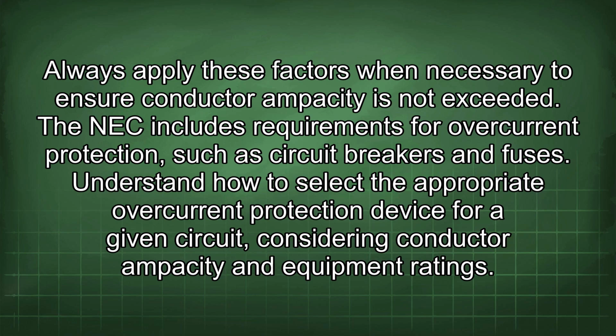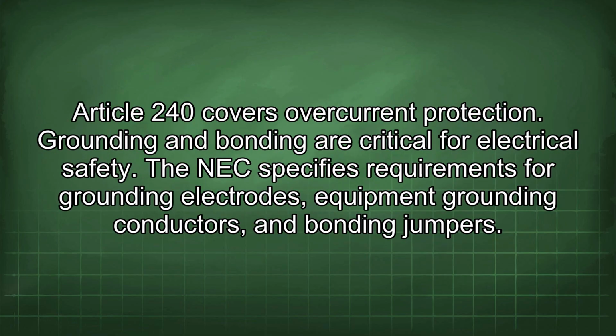The NEC includes requirements for overcurrent protection, such as circuit breakers and fuses. Understand how to select the appropriate overcurrent protection device for a given circuit, considering conductor ampacity and equipment ratings. Article 240 covers overcurrent protection.